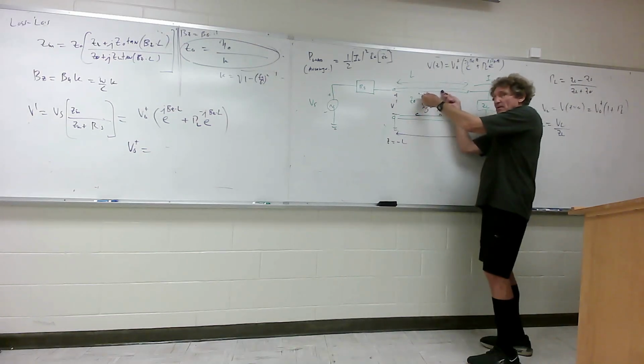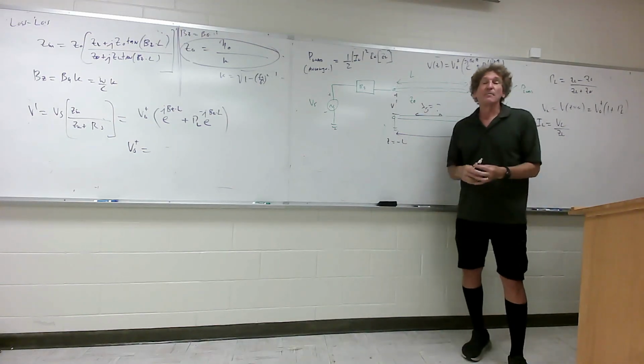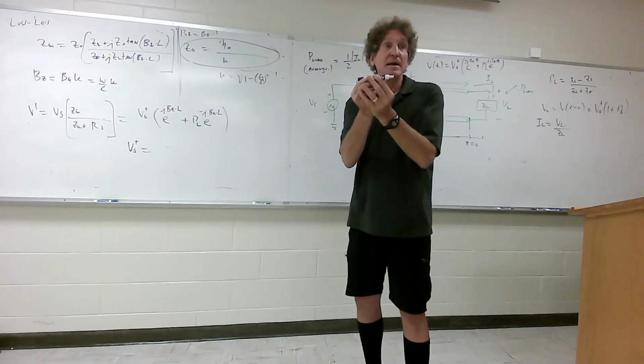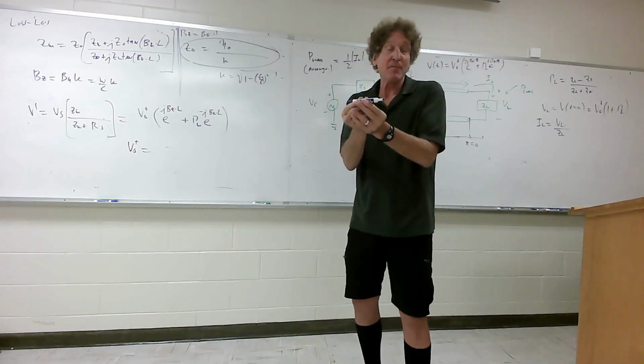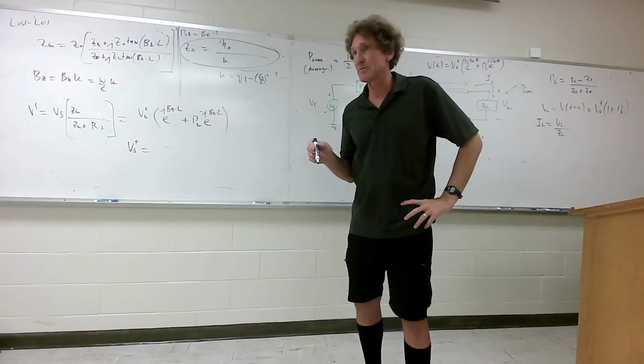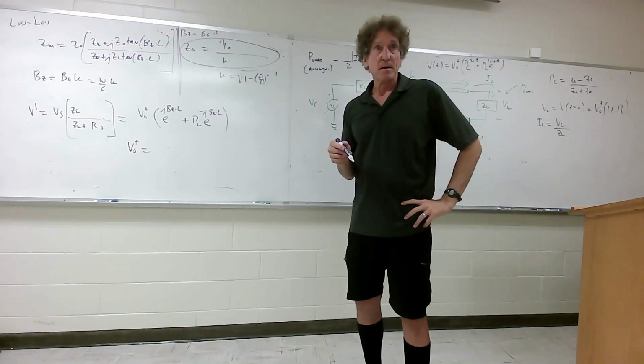Wavelength from here to here would be a wavelength, right? The projection in that direction, well, you can't probably see it the way I'm talking about, but it'll be infinite at cutoff. It literally, the wave is just bouncing up and down. There ain't no projection of wave. It's hard to see this sometimes, but play with it and I promise you will. Beta goes to 0 at cutoff.